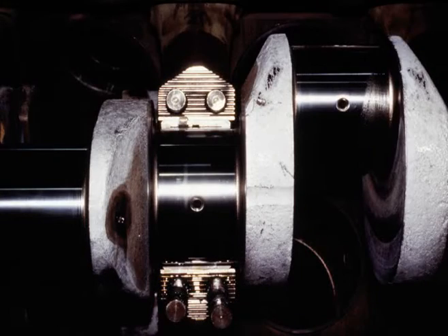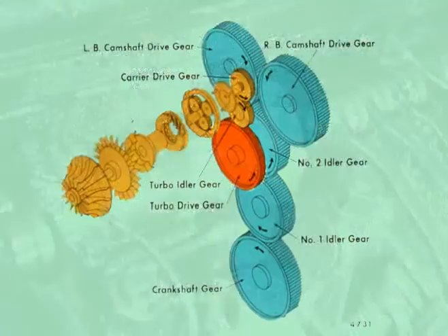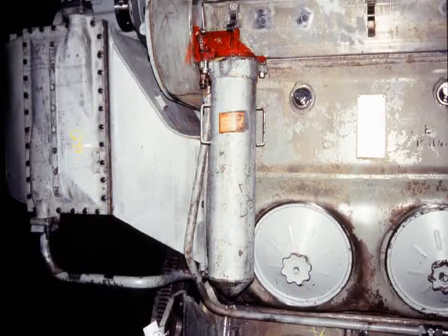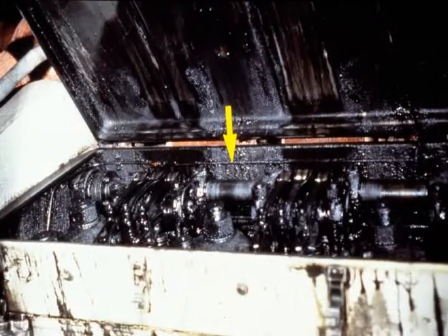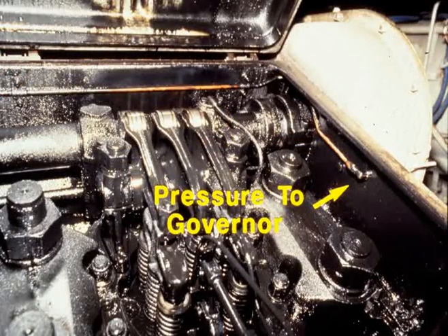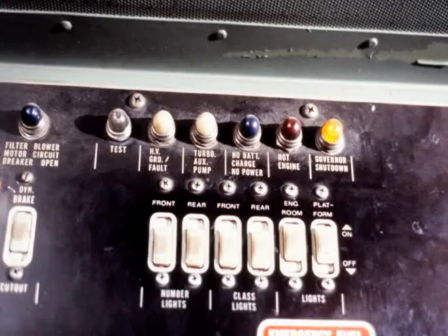The main lube oil system lubricates the crankshaft and main bearings, the camshafts and valve train components, and the rear gear train and turbocharger bearings. A final filter is used to clean the oil before entering the turbocharger and gear train. A sensing line from the output of the turbo filter delivers pressurized oil to the engine governor. If pressure falls below 30 psi in notch 8 at operating temperature, the governor will initiate a shutdown, and a light will glow on the engine control panel.